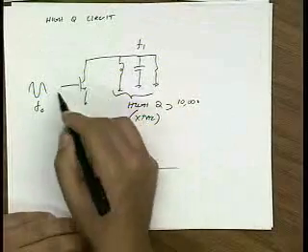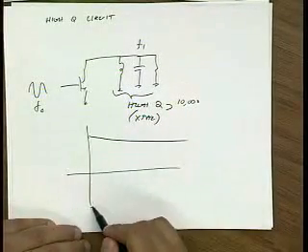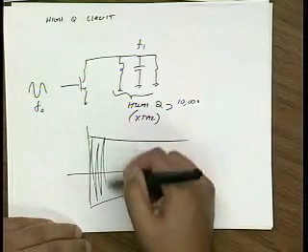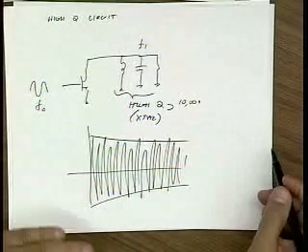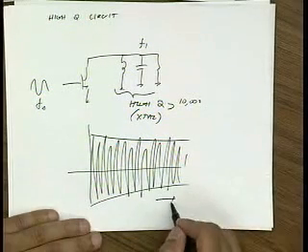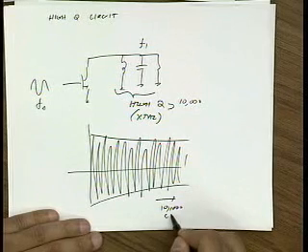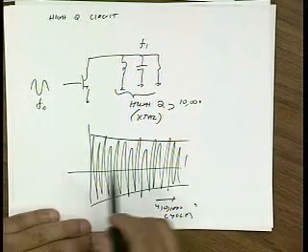So if I just turn this circuit on, it'll start ringing like a bell. And this ringing can go on and on and on, for 10,000 cycles, right? So if I'm doing a transient, I'd have to wait roughly 10,000 cycles until the transient dies off.